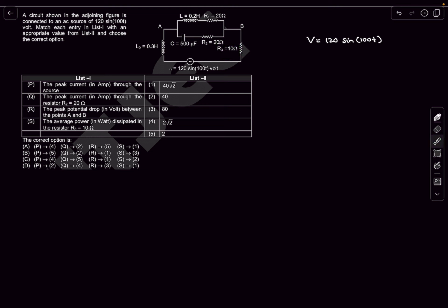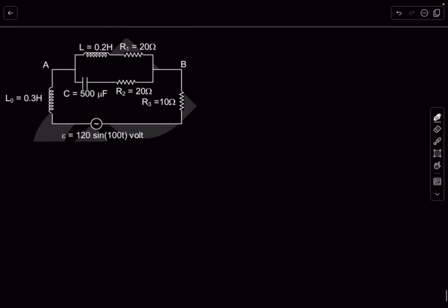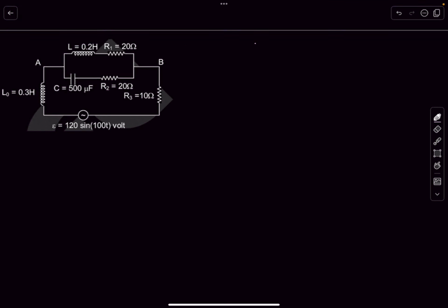So we are going to be using the complex number method to analyze the AC circuit. We'll discuss a few concepts before solving the problem. So let's say when we are given a sinusoidal voltage, let's take a random one of V0 sine of omega t plus phi. So you guys might be knowing, if you write the KVL equation for this loop, you'll have to solve fairly complicated differential equations. You have to make multiple equations and the differential equations become quite complicated. So what we do instead is we use phasors to simplify our analysis.